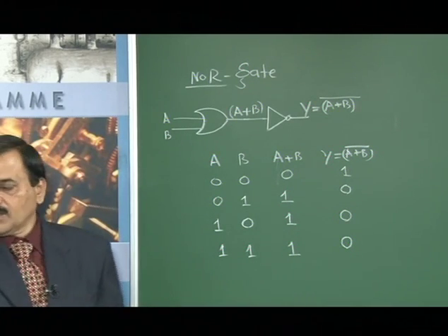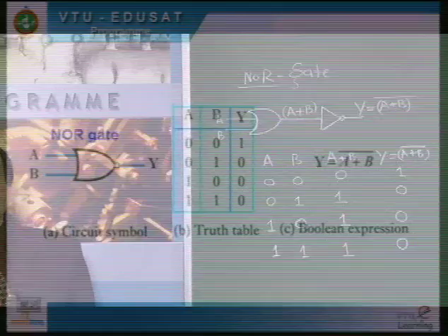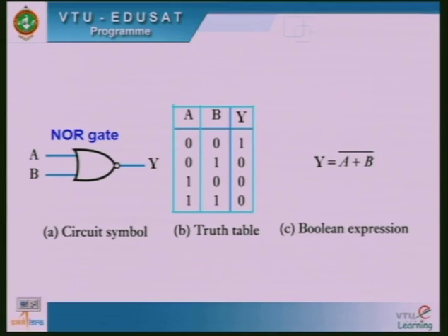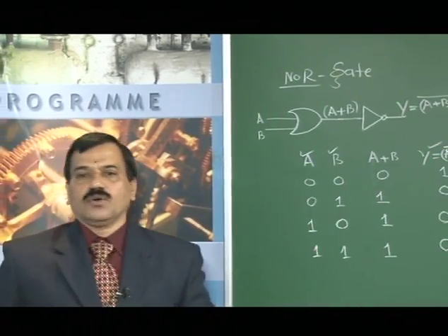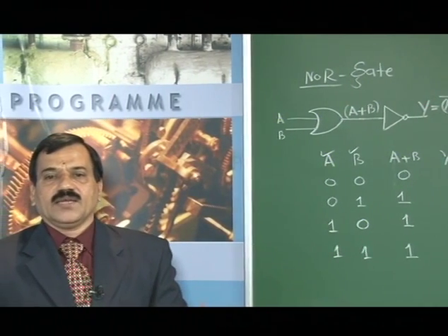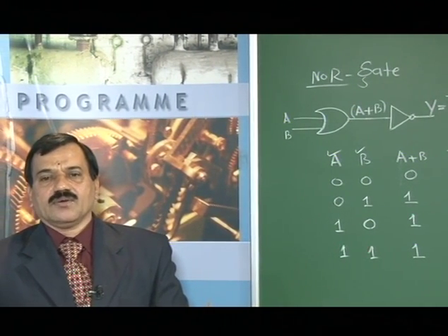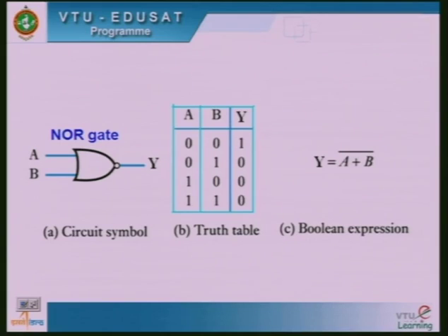Hence in the truth table of this we can see 0 0 is equal to 1. Finally we are going to write only these things. So only these three, so that y value 0 0 is equal to 1, and 0 1 is equal to 0, 1 0 is equal to 0, and in the last line both inputs are high, then the output is treated as 0.